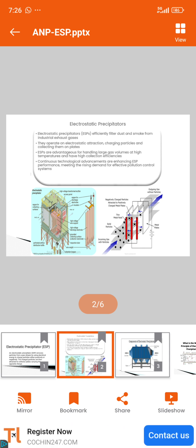In this slide, the first figure shows an actual electrostatic precipitator as present in industries; such a big piece of equipment is there in every industry to remove dust particles. The second image shows the same working principle. You can see the blue arrow from the bottom, showing that the gas stream is blowing through these electrode plates, all the particles are precipitated on these electrodes, and at the top only clean air passes through.